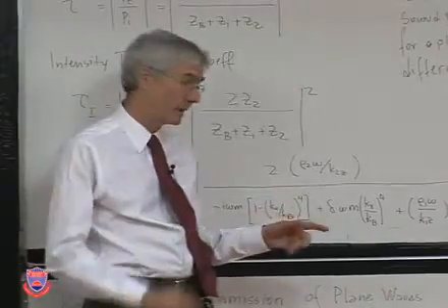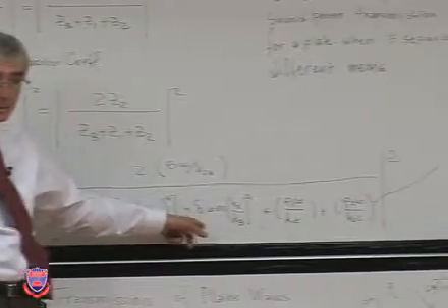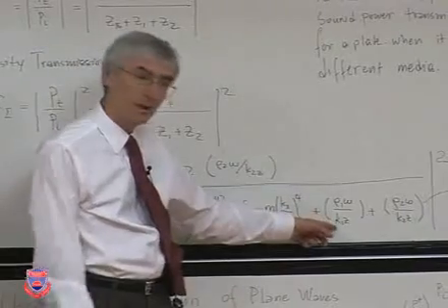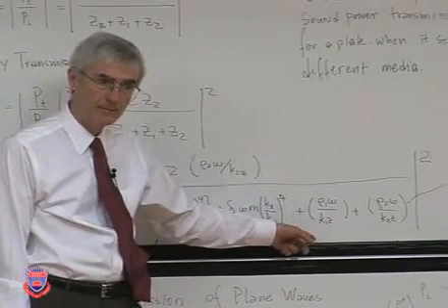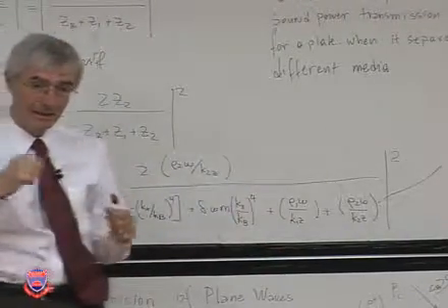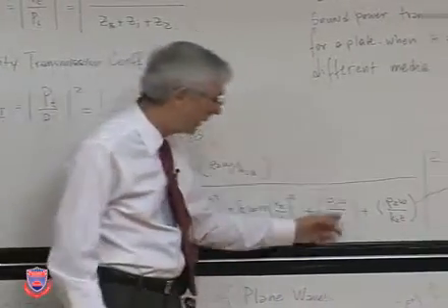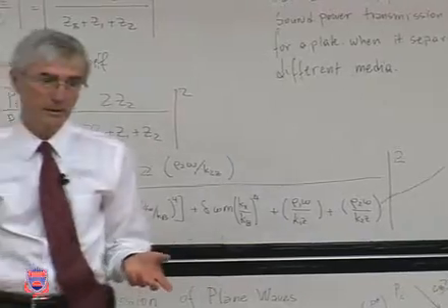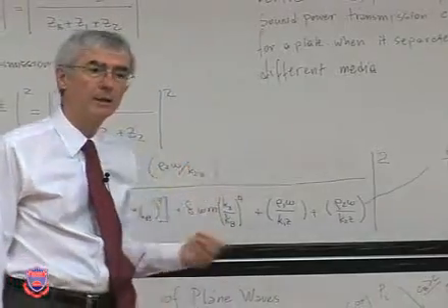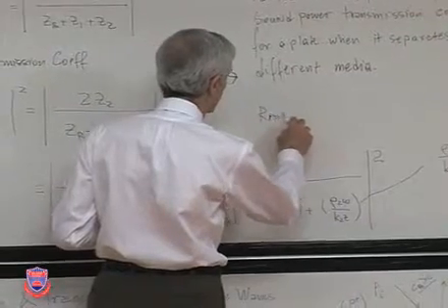So some of the incident energy excites the plate. As a result, there's plate damping. Okay? Just like what I demonstrated earlier, which you didn't see. And what do these do? They radiate sound away. Okay? Some of it is reflected back, some of it is transmitted to the other side. So radiation of sound is a damping. In fact, in making calculations, radiation damping is a term. Okay? So you can call it radiation damping.